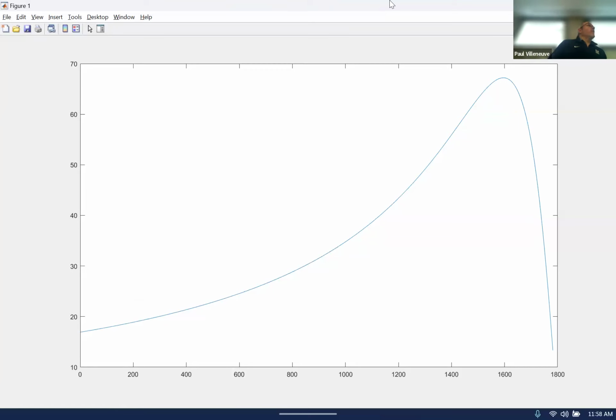All those torque versus speed characteristic curves that you see for motors are generated after somebody has done a locked rotor test, a DC test, and a no load test. They got parameters for it, and then they literally just plot it like we did here. That's all they do. You cannot get this type of curve in the real world. But you have another way of plotting. It makes it pretty easy.